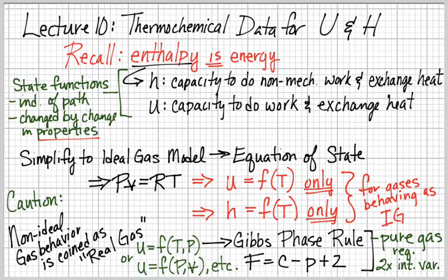the equation of state, or the way that we solve the energy change for water vapor, will require 2 independent intensive variables, which is why you see on the left side of this in green, the U internal energy is a function of temperature and pressure, or the molar internal energy is a function of pressure and molar volume, etc. You'll see these 2 variables that are required, and we plot them on a 2-dimensional plot quite often.